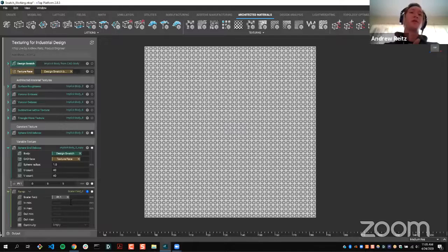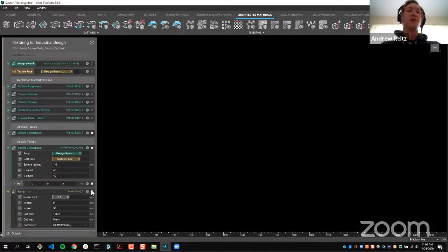And then what I want to do is to say, okay, if you're on top of this point, or if you're near this point, so 0 millimeter, I want the sphere radius to be 1 millimeter. And then I'm going to go back here and say, as you move away, and I know my swatch is about 100 millimeters, so let's say at 50, I want your radius value to be nothing. And then I'm just going to select the first option here, which is a linear falloff.